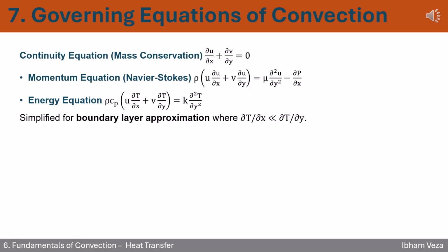7. Simplify the governing equations. Understanding convection starts with 3 fundamental equations. Continuity equation governs mass conservation, ensuring fluid in equals fluid out. Momentum equation, Navier-Stokes, governs how velocity changes due to forces like pressure and viscosity. Energy equation governs temperature distribution within the flowing fluid.